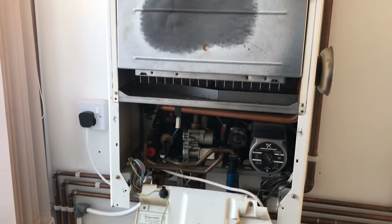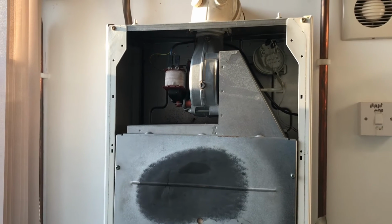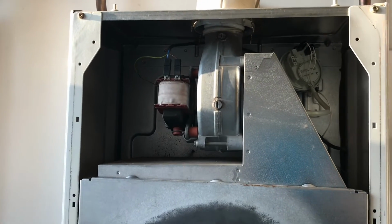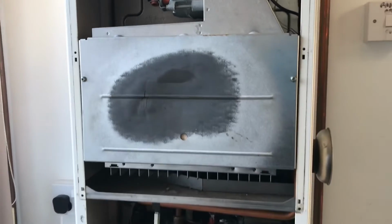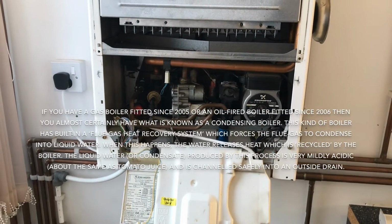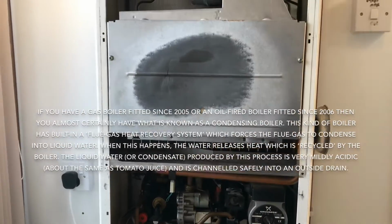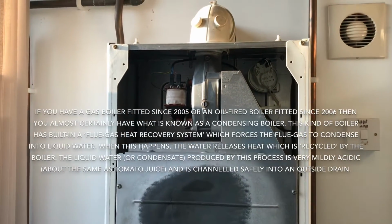Now then, this is the next progression in boilers. The boiler we've just looked at was balanced flue. This one is natural draft, but we've got a fan flue on this now, so we're going to the next stage up. A difference as well is this is actually a combi boiler, not a heat only boiler like the others. The other boilers we've looked at would require cylinders. This wouldn't require a cylinder as it's a combi boiler, which would heat hot water and heating.